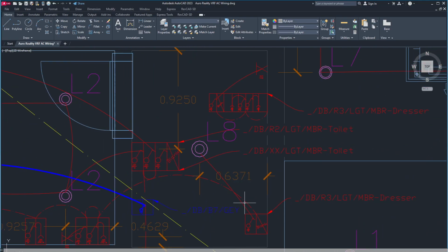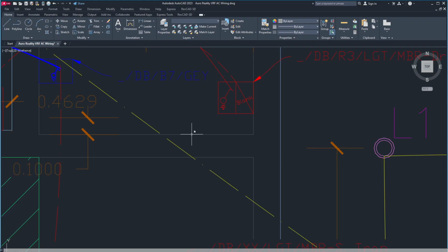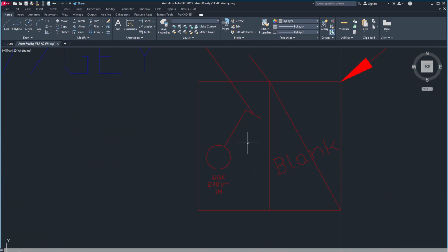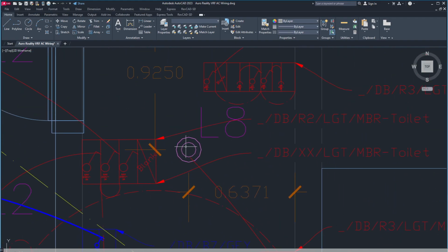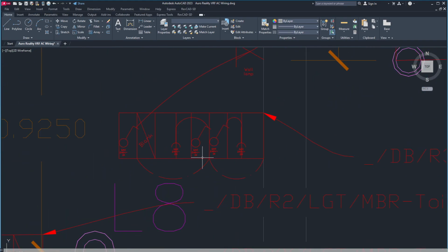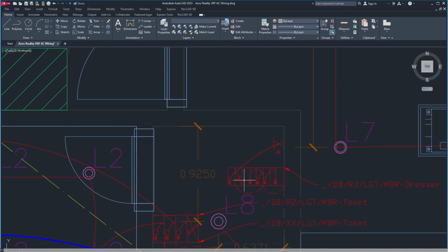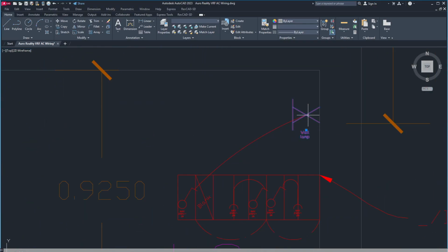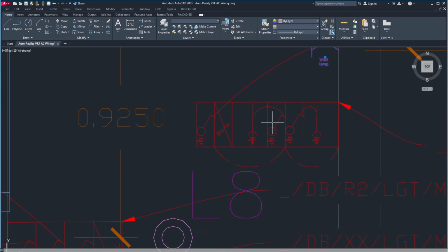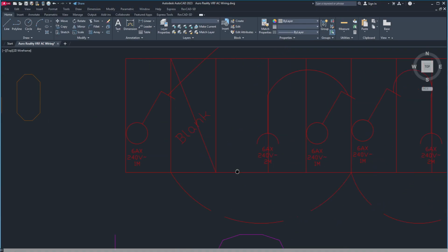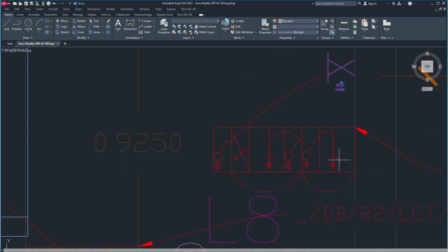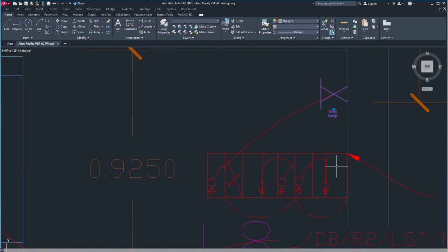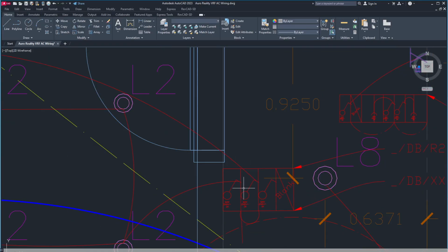So this is a dresser. In the dresser, people walk like this. On the right hand side, there is a switch and a blank. Turn on the switch, this light lights up. You come forward, and here we have something interesting. We have a light behind the mirror. This is the light behind the mirror, we can assume. Then this is the switch controlling that. We have a blank, and we have two sockets, because they will run hair iron, hair drying machine, and several makeup machines are there. So those activities will be done here, so that has to be provided there.